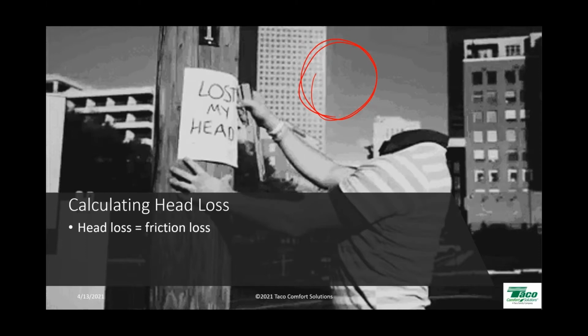So think of a Ferris wheel, okay? If you're sitting on this cart on the Ferris wheel, does the motor on the Ferris wheel have to lift you up? No, because there's some other guy in the cart over here coming back down, all right? So the weight of the water is kind of like a counterbalance. I don't have to lift the water up to the 3rd floor. It's already there. We've already filled and pressurized the system. All the circulator has to do is quite literally circulate the water. We call them pumps, but really they're circulators.